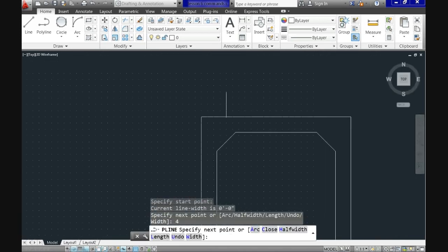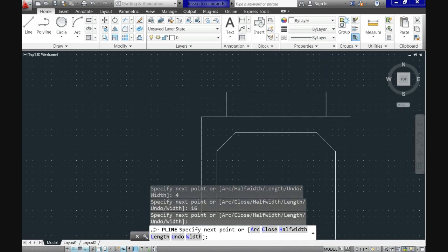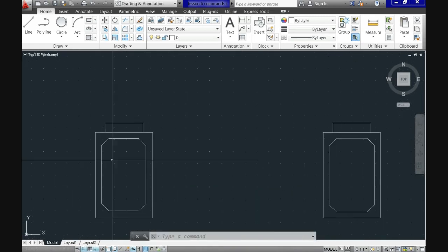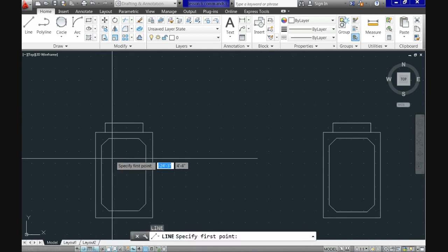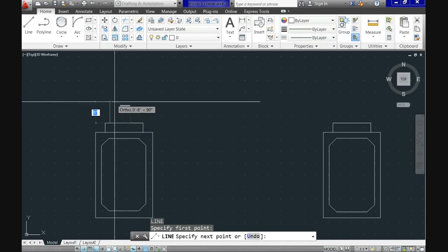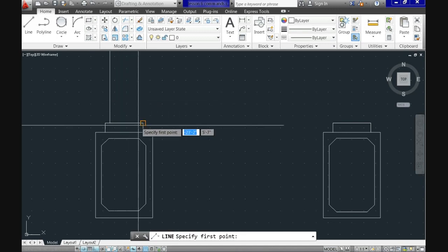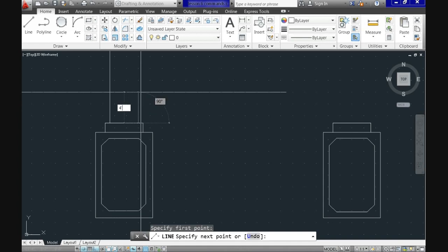And now let's do the columns on top of the bases, and we'll do it 4 inches from each one of the edges. We'll use the line command and we'll assign a 4 feet height to it. But as you will see, it really doesn't matter whether you use line or P-line for individual straight lines. So for the other 2 columns shaft, I will use the command P-line.